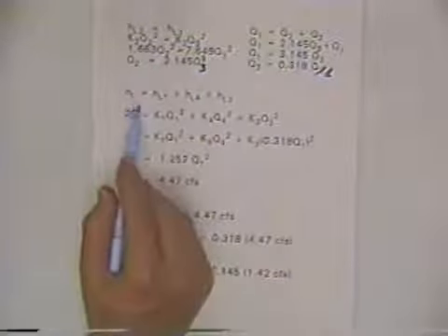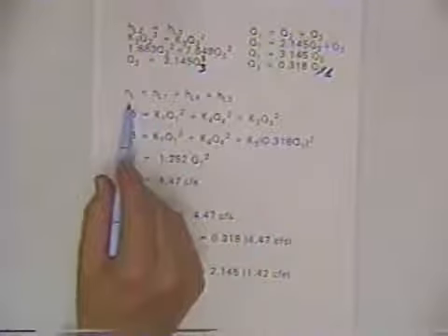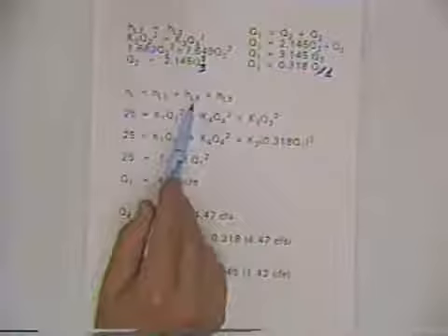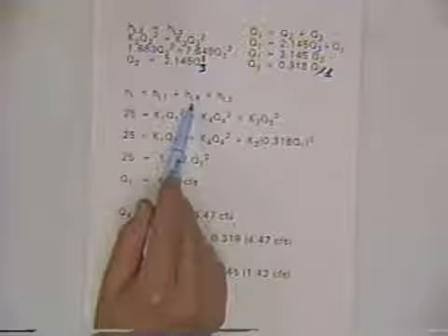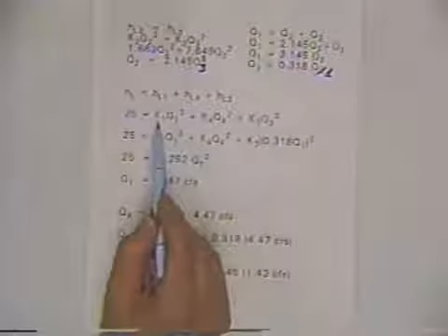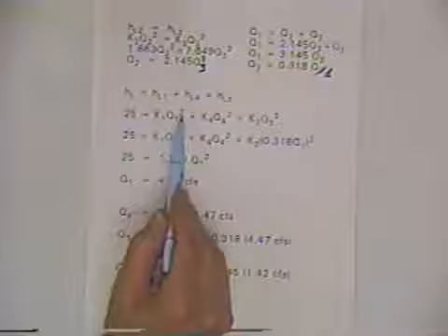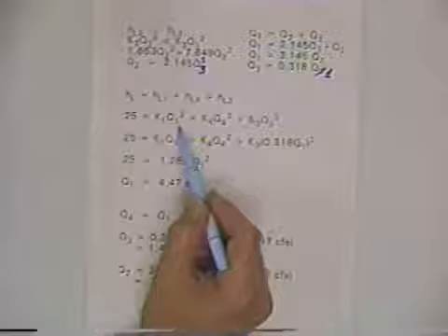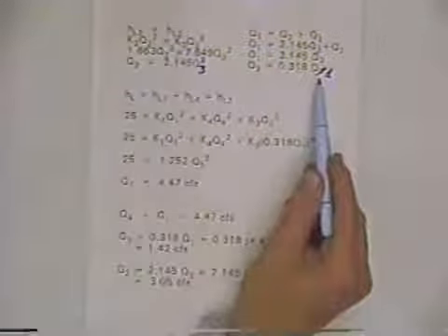Now, the other thing we know deals with head losses. We know that the total head loss from that one point to the other end of the system is just the head loss in the first pipe plus the head loss in pipe 4, and then I chose to use pipe 3 along that path. And head loss is always K times Q squared. The K's are just numbers from Darcy-Weisbach. And so we've got 3 unknowns, Q1, Q4, and Q3, but this allows us to substitute in.